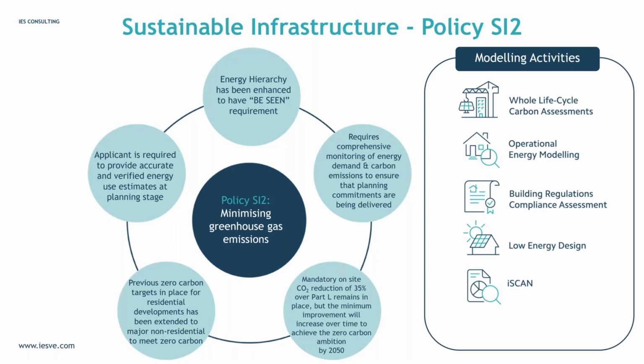In addition to the requirement to consider operational energy, there is also a requirement for major developments to have a minimum on-site reduction of at least 35% beyond building regulations. Residential developments should achieve 10% and non-residential developments should achieve 15% through energy efficiency measures, with any deficiencies being made up through a variety of planner-agreed measures when the net zero carbon target cannot be achieved.